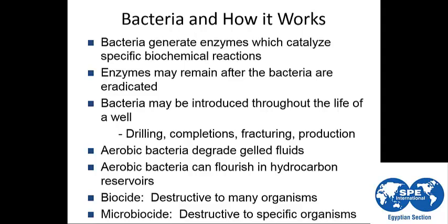So if you have bacteria inside the water that you are going to use for the frac fluid, this may result in early breaking of the gelling agent. So we use biocide to avoid bacteria and their enzymes, which affect or may break the cross-linked gel.